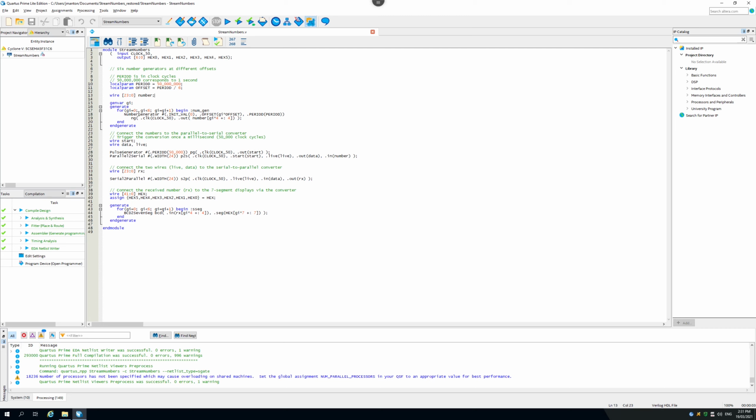Instead of writing out 6 number generators here, so remember each of these is going to be a physical chip, so to speak, I could have just instantiated 6 of them, and 6 isn't too bad. But if I had 600, I would not be doing it by hand. So I showed you here how to use a generate block to allow you to generate more than one of the same thing. And it's better than more than one of the same thing: we can make slight variations to each one, which is what we need.